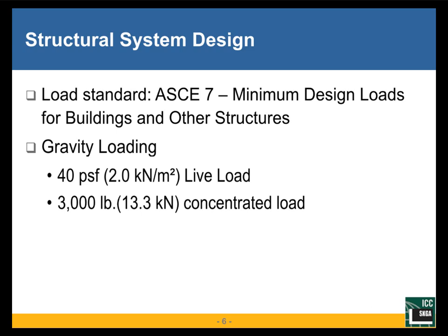There is some concern going forward that the vehicles that were studied in 1999 may not be the same as what is coming forward now, and yet the load was reduced. That study considered that the uniform parking load based on the survey could have been 35 pounds per square foot. Certainly with the advent of electric vehicles, we're concerned that the vehicles may weigh another 1,000 pounds greater for the weight of the batteries that are going into them.